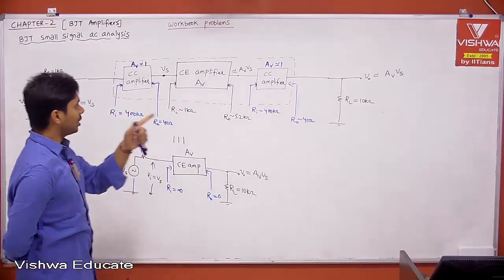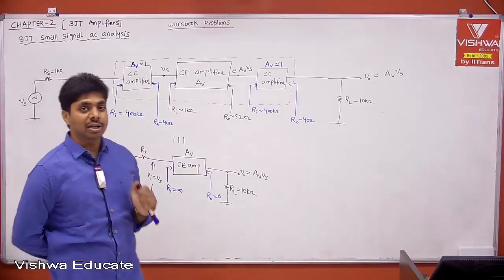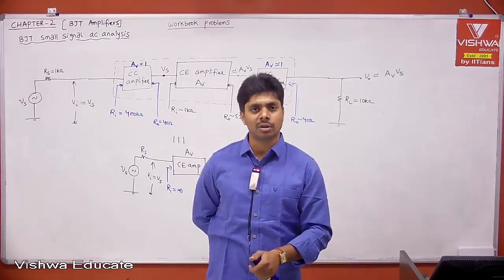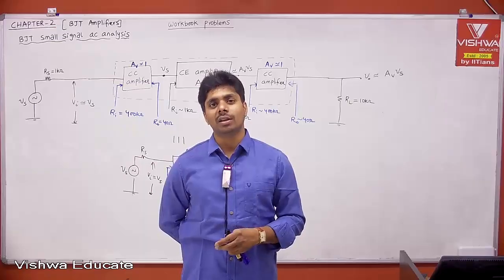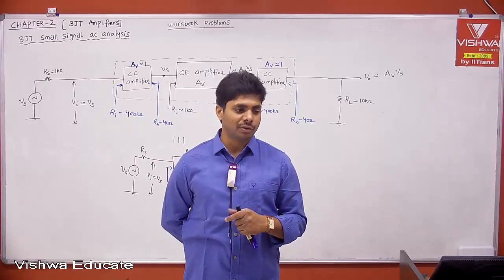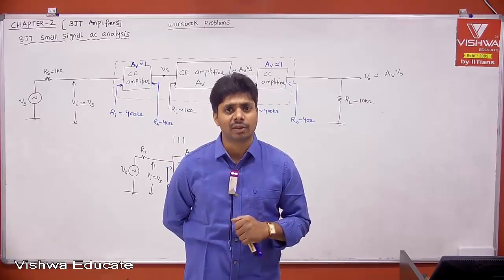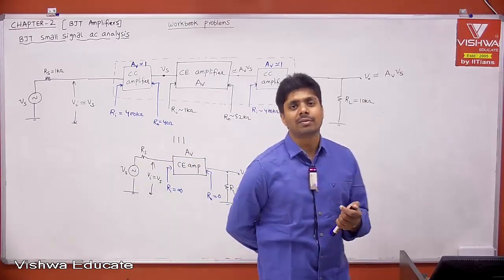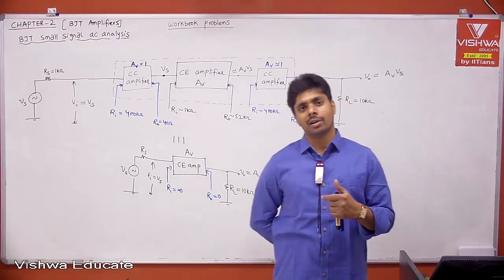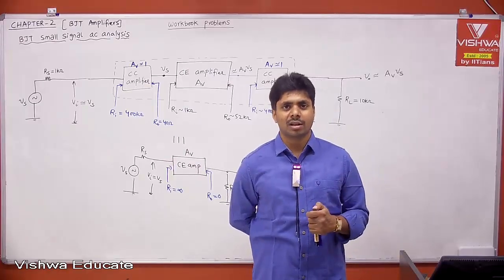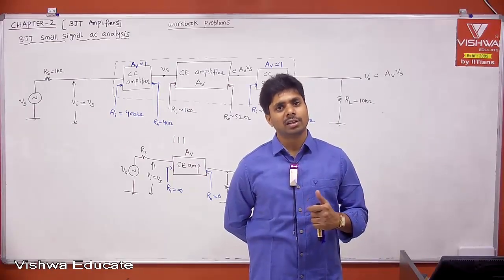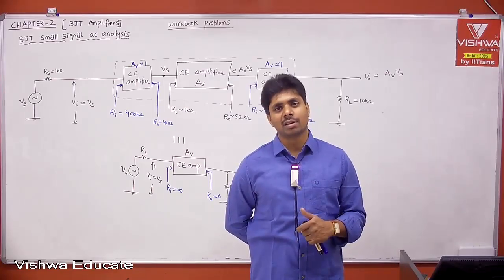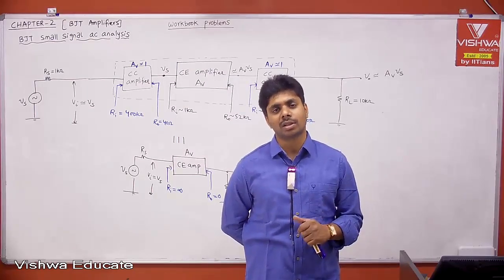Here, if you take your op amp, it is nothing but your generic amplifier having very high or infinite voltage gain, infinite input impedance, and zero output impedance, right? That needs only a number of transistors in the order of maybe less than 50. But if you add the remaining things, like if you take the IC 741 op amp, the internal circuit has offset cancellation, calibration, and the biasing circuit, etc., there are approximately 108 transistors.